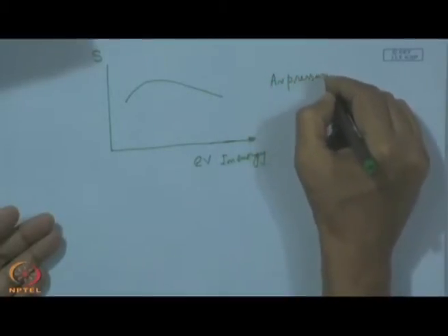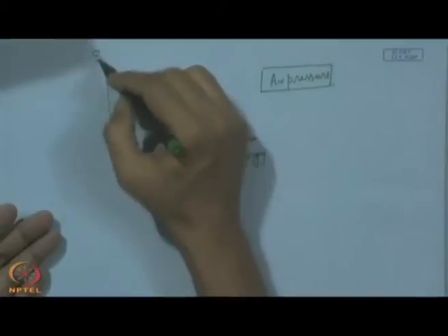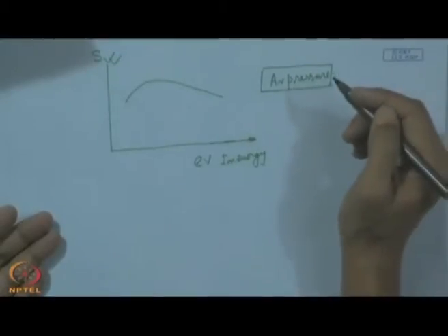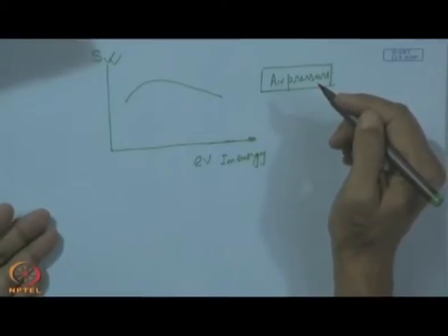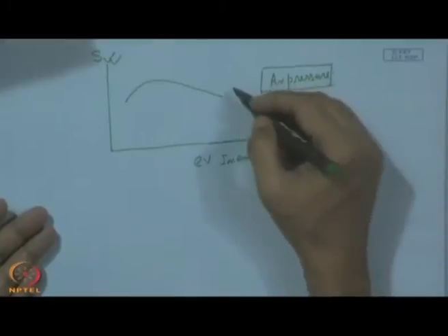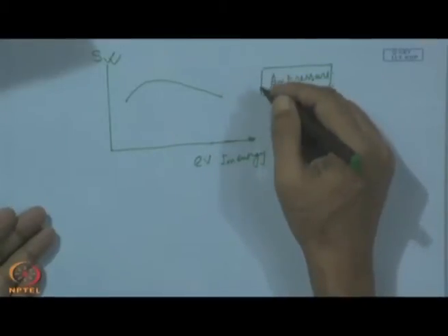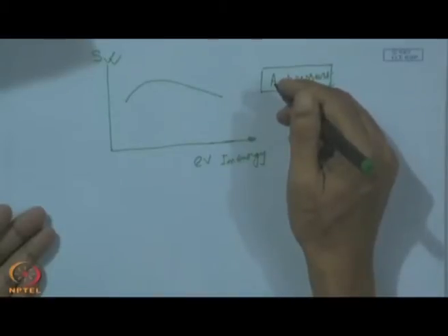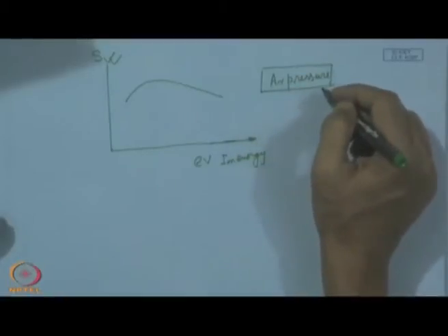However, there we can see definitely an increase in sputtering yield with increase of pressure, but too much increase of pressure also restricts the mobility of this sputtered flux of atoms from the target, and easy movement of the ion or the electron is also restricted because of the too much crowding of argon atoms inside, and that is because of this rise of the pressure.